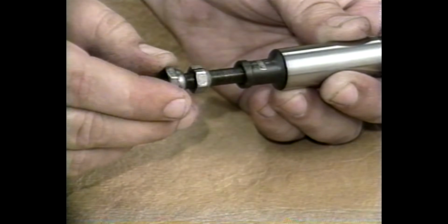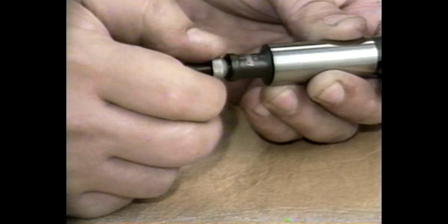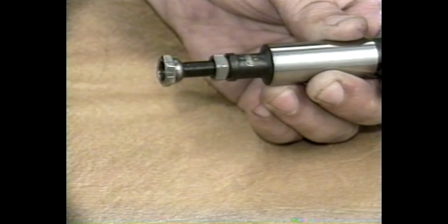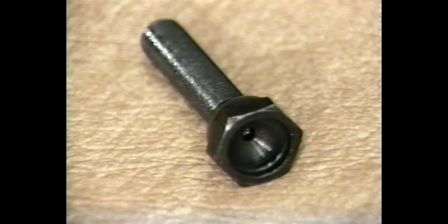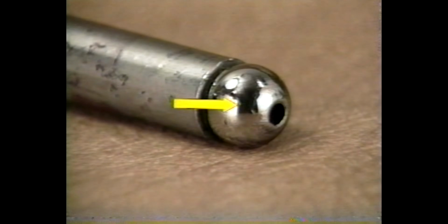When we use solid push rods with solid lifters, each lifter must have an adjustment screw and lock nut that we can use to provide the necessary valve backlash clearance. In Evolution engines, the solid lifter adjustment screw must also have an oil hole through it to allow the lubricating oil to flow up through the push rod to the rocker arm.